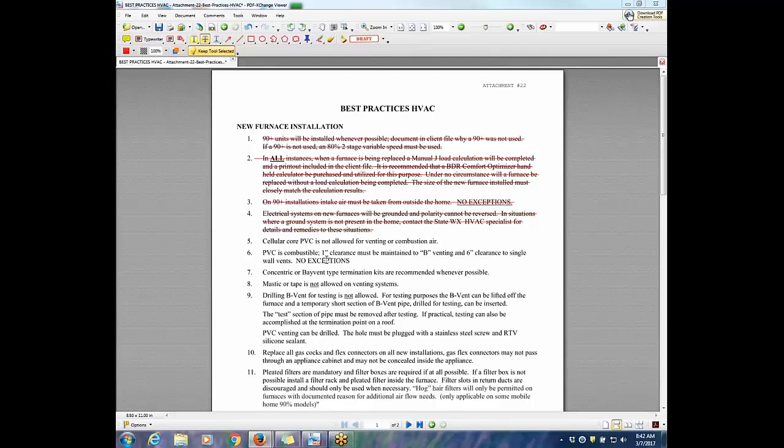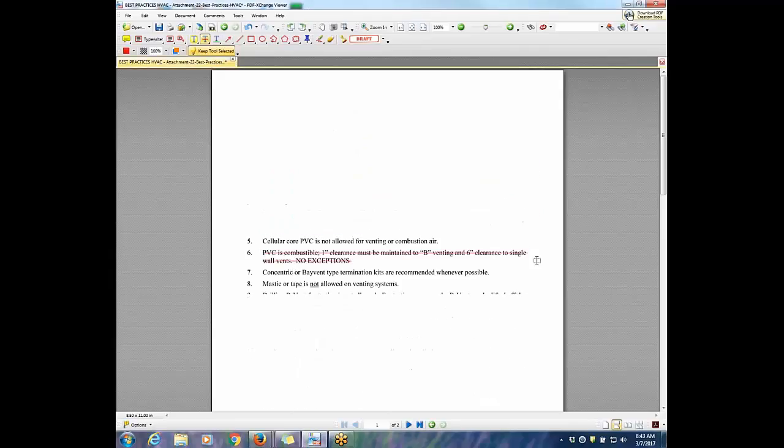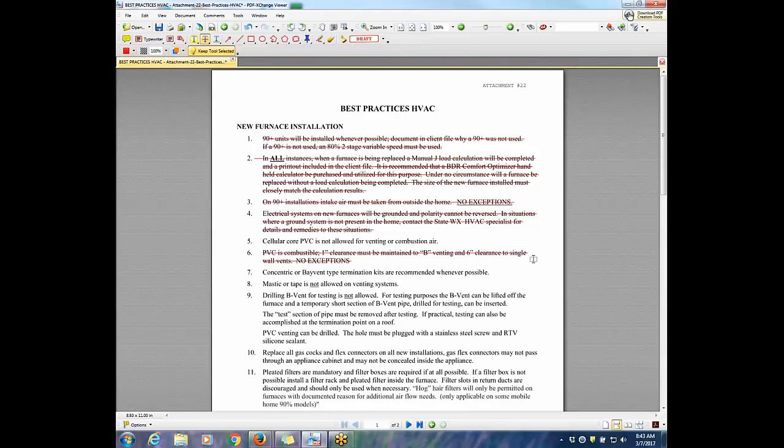Yep. So again, I don't know that this needs to be said. It's just part of understanding your furnace training and RMGA. Clearance from combustibles. PVC is a combustible. So I think it's a redundant statement. I'm pretty sure it's covered in our field guide too. Follow manufacturer's venting instructions along with the National Fuel Gas Code. Okay.